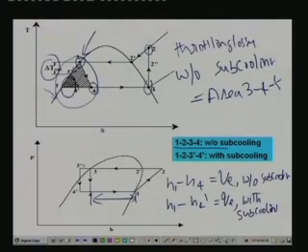It also has other benefits. Let us look at what the other benefits are. You can see that the exit condition of the condenser is very much in the subcooled liquid region. So this will always ensure that only liquid goes into the expansion device. Remember that process 3-4 is the expansion process or throttling process. When you don't have any subcooling, the inlet condition is just saturated liquid. If some change takes place in the condenser, there is a possibility that this point will shift this side and the inlet condition will go into two phase.